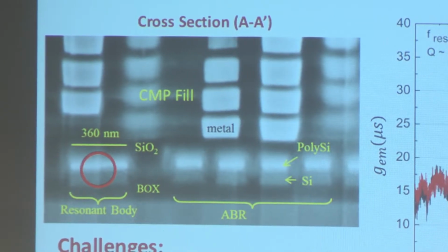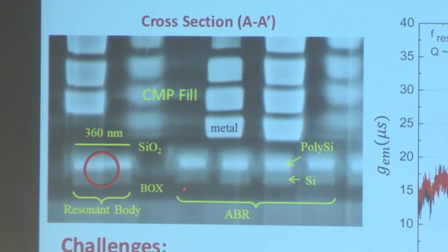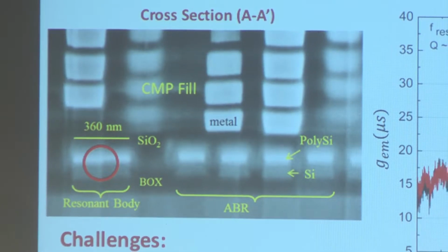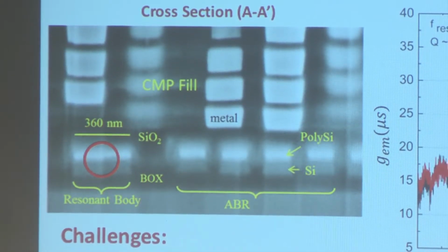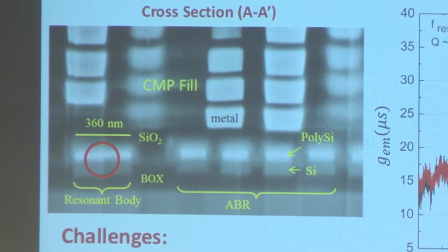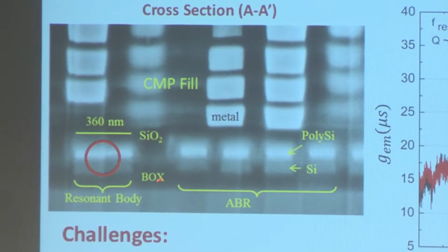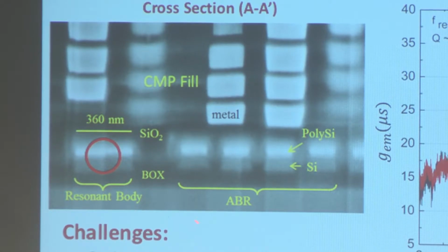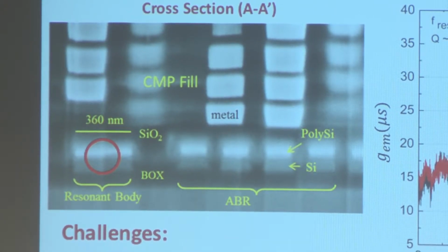The second problem, if we look closely at the Bragg reflectors, they are actually very thin. This thickness is probably 100 nanometers or something like that. So as a result, we found that the vibrations in this resonator start radiating out all the way on top and the bottom.